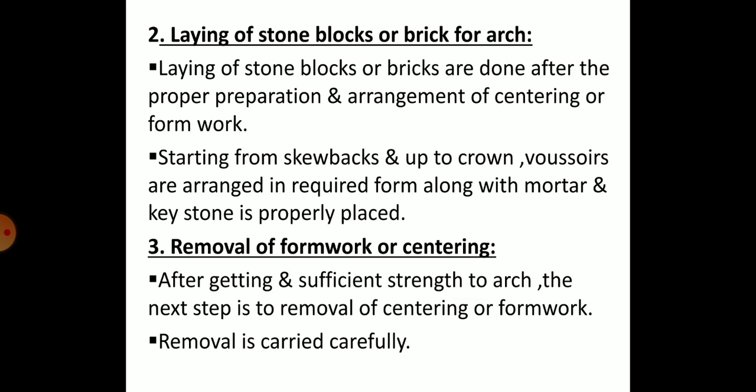The next is the laying of the stone blocks or bricks for the arch. The laying of the stone blocks or bricks is done after the proper preparation and arrangement of the centering or formwork. Then, starting from the skewback up to the crown, the voussoirs are arranged in the required form along with the mortar, and the keystone is properly placed.